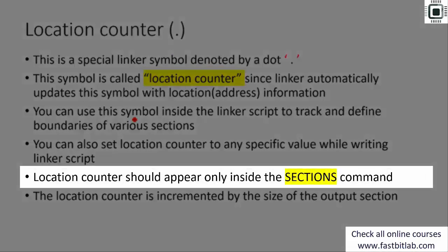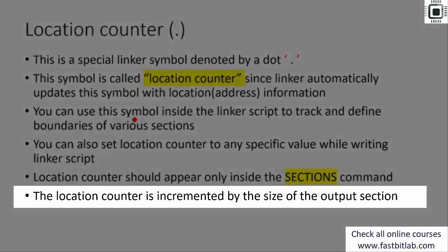Location counter should appear only inside the sections command. You have to remember that. So you cannot use that outside the sections command. That would throw you a linker error. The location counter is incremented by the size of the output section. That helps you to track the boundary.